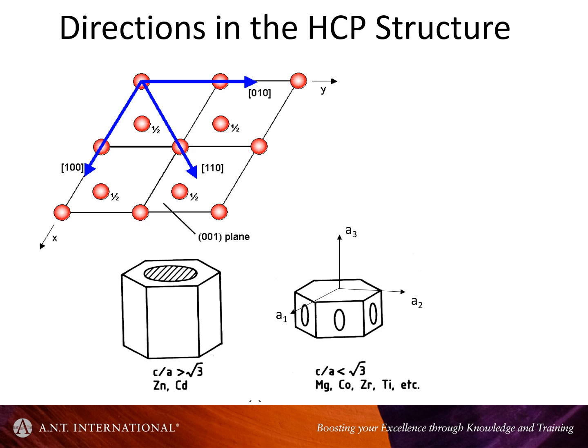I have to address a little bit of crystallography and symmetry just for completeness. Some of you may appreciate this, some would just switch off a little bit. But how are the atoms arranged in the HCP structure? Well, this is typically how one would describe the crystal structure or the symmetry of a crystal structure. And the unit cell is actually the smallest arrangement of atoms that can be translated to produce the whole crystal. It is actually this rhombohedral prism in this case.